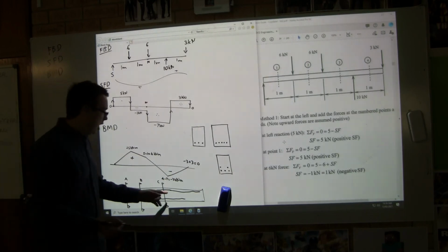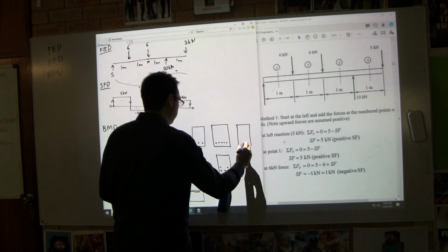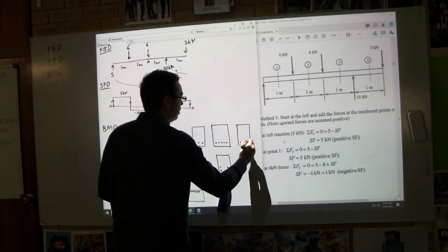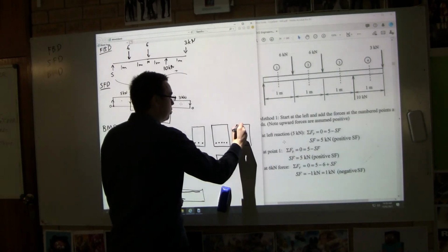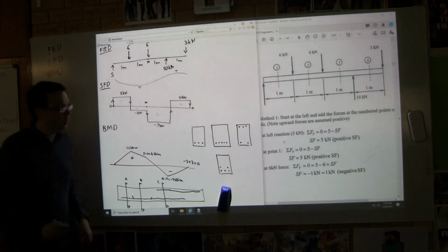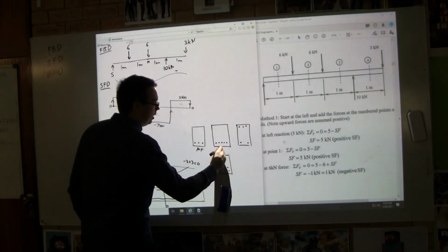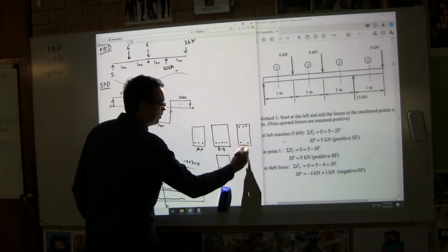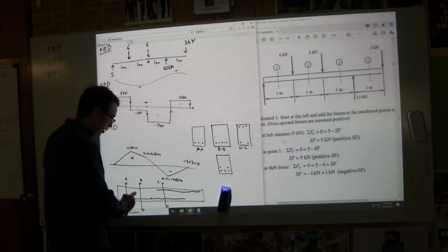And then finally at C, we're back to needing only our bare minimum of steel at this point. Maybe just get away with 2 bars, and then we need a couple of bars up the top. Maybe we put 3 bars up the top. Yes, that's our section at A, B, and C. Yeah, and that's an alternative version of B. It's not what's shown here. That would look like a line above.